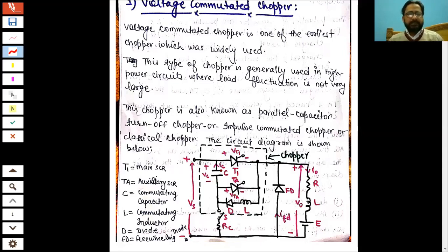Now, how is it possible to have VC across the capacitor? That can be the question. So there is a provision made basically. You can see there is a switch connected here and there is a resistance RC. C here is for the capacitor. So the main purpose of this RC is to limit the current basically, when the capacitor is connected across the main supply.